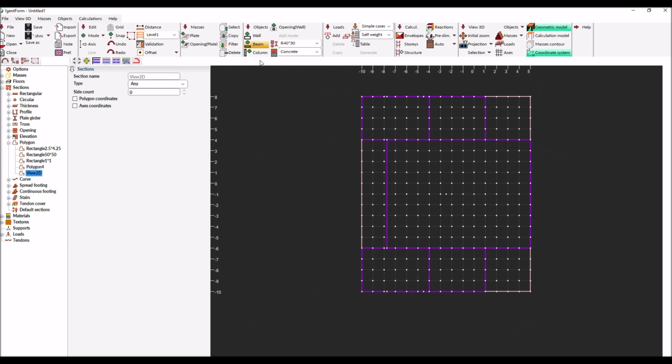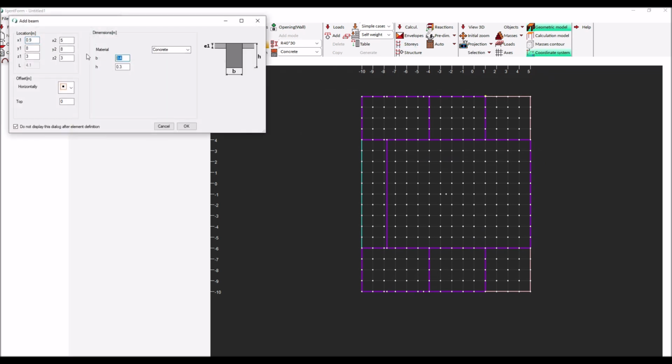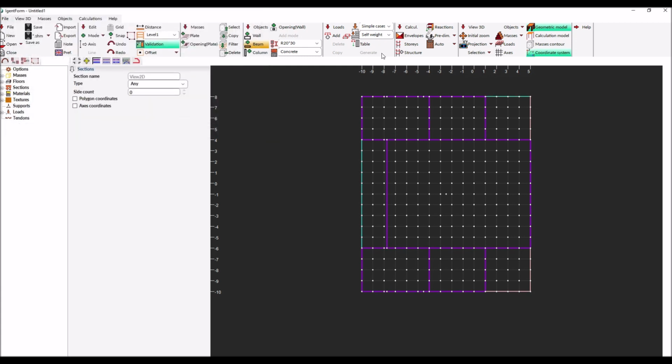Now beams will be added to our model. As for walls, we can use polyline mode. However, in this case, standard mode is used. After clicking the beam option, in the graphic menu we see near it an icon which shows the current mode: add, delete, select, change node position. These modes are easily available in the context menu on 2D view.